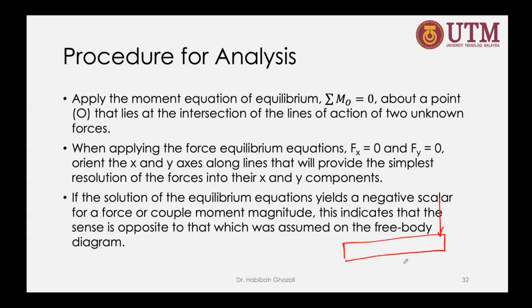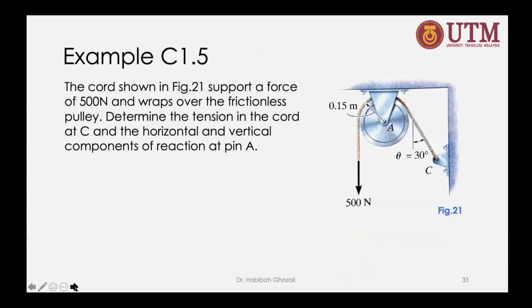I have an external force going upward, an external force going downward, and here I have a fixed support. So with a fixed support, we said it's going to resist in X direction, it's going to resist in Y direction, it's also going to resist rotation. So you can assign this whichever direction you want, but when you do your calculation and you get negative, it means that what you assumed here should be the other way around. So that's how we analyze the reaction, static equilibrium equation.